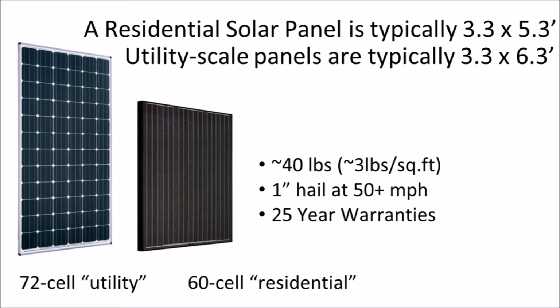So residential rooftop solar will have the 40-pound, 3 1/3 by 5 1/3 foot, 60 cell solar panels, typically, again, because they're easier to manage on a roof. On ground mounts or flat commercial projects, the larger 72 cell panels have slight cost advantages. A few specialty module manufacturers might deviate from these standards as well, and 72 cell modules are allowed on residential roofs. They're just a little harder to manage.